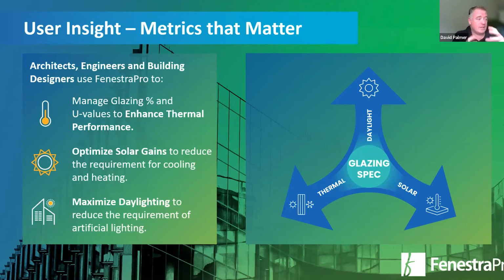So where you've got a lot of glazing, you also get a lot of solar gain. And that's a good thing in some ways, but obviously you've got to manage and control that so you're not overheating the building and therefore relying on additional cooling to control the environment within it. And again, where you get a lot of glass, we're looking at how we can maximize the amount of daylight coming into the space and ultimately try and prevent glare.